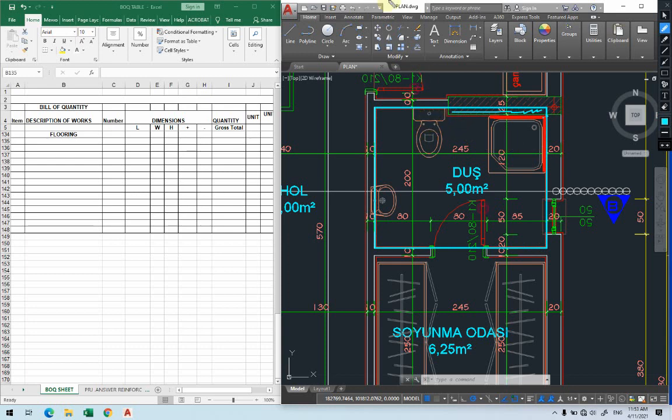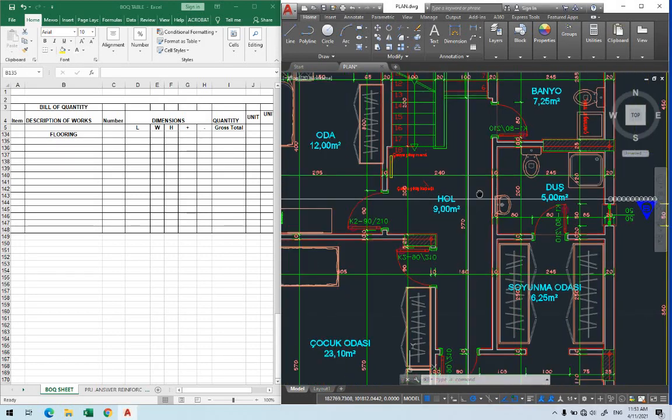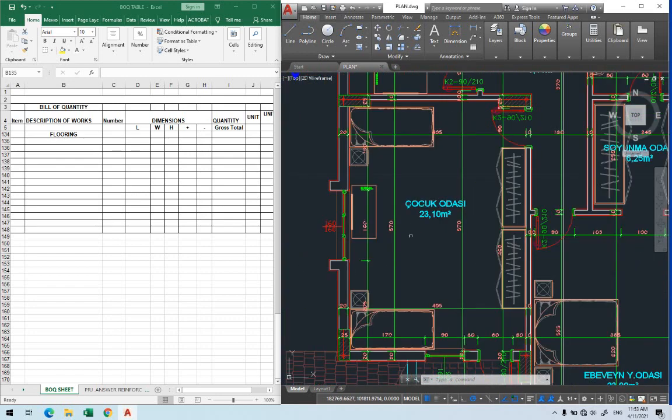Now if this area is given to us, I can use this area exactly to calculate the tiling here. So for example, flooring, I can write tile, whatever the layer under it is, I can simply write this one as 5 square meters, and that's it. Or if the area is not there, you'll calculate the area and take this one out of it. That's why most of the plans now have the area inside them. But you have to be careful. Check whether this area takes care of this small corner, and if so, use it directly. If not, take care of these small corners by yourself.